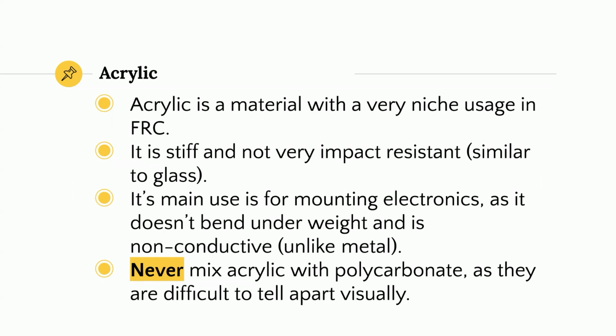The one tip with acrylic is never mix acrylic with polycarbonate, as they are difficult to tell apart visually. The best way I've found is that the sides of polycarbonate have a slight blue tint to them if you look in certain light. Yeah, slight blue tint. That's your way of figuring it out. So just don't mix them.